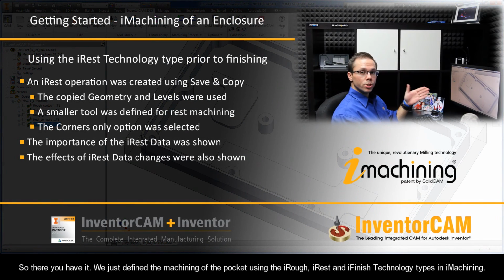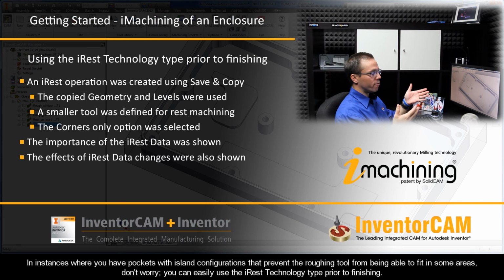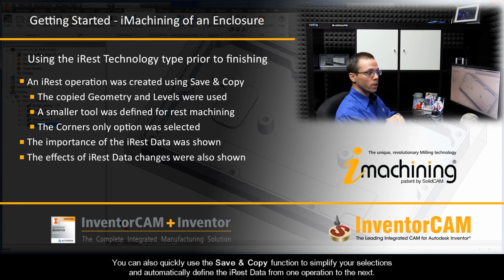So there you have it. We just defined the machining of the pocket using the iRough, iRest, and iFinish technology types in iMachining. Now, in instances where you have pockets with island configurations that prevent the roughing tool from being able to fit in some areas, don't worry. You can easily use the iRest technology type prior to finishing. You can also quickly use the Save and Copy function to simplify your selections and to automatically define the iRest data from one operation to the next.